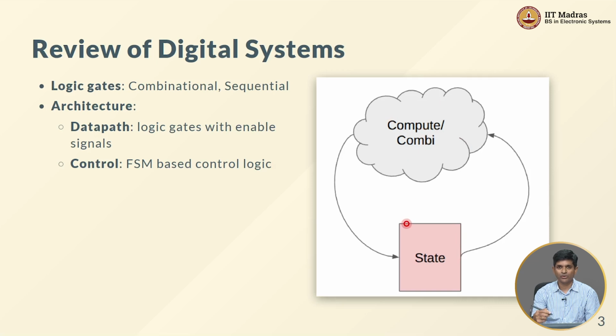This picture is an oversimplification because I might find that I am actually implementing something like, let us say, a sequential multiplier, where clearly the compute is not just combinational, but there I am making the difference and saying that the sequential multiplier is this entire system, it is not just the compute alone, right. What I mean by that is, since a sequential multiplier takes n clock cycles to multiply two numbers together, it means that some part of the state is being retained as part of the multiplier, right.